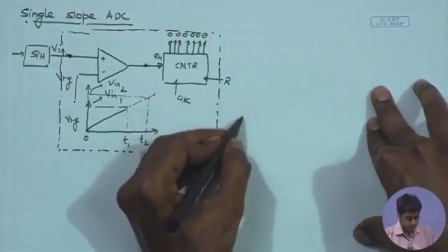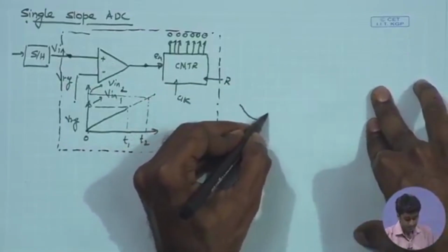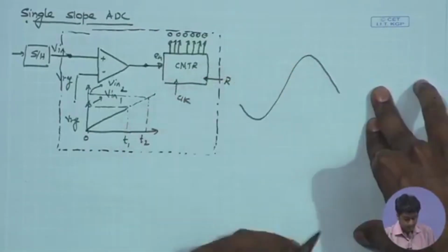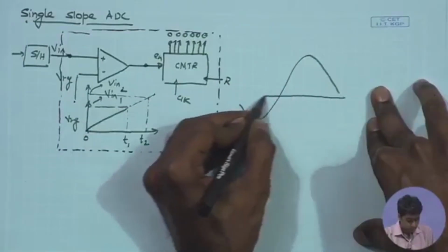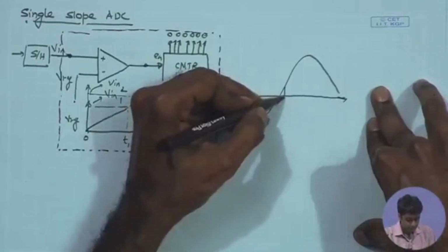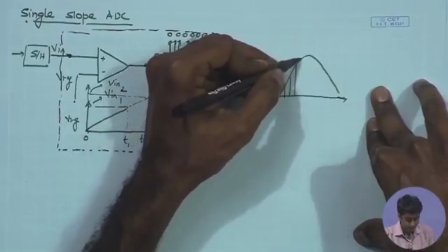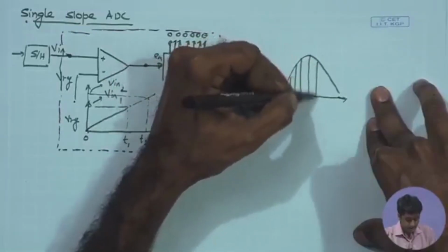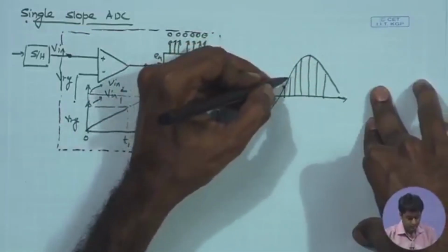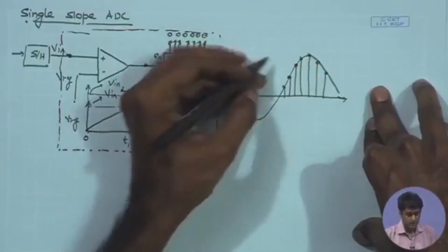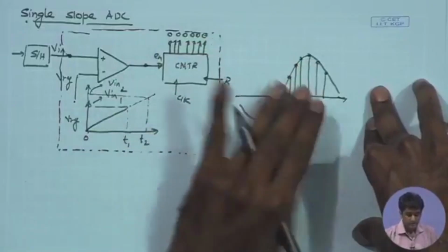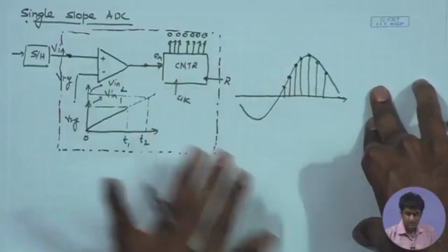So, if you have continuous time analog data coming in, we need to first of all, in the time domain, sample the continuous time data at specific instances and then obtain the digital value corresponding to these samples. And we know that the maximum sampling frequency is determined by the Nyquist rate.